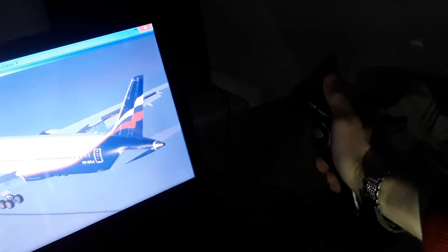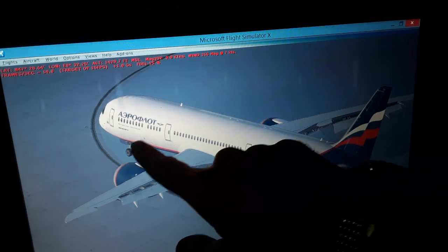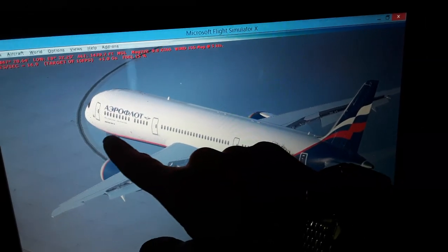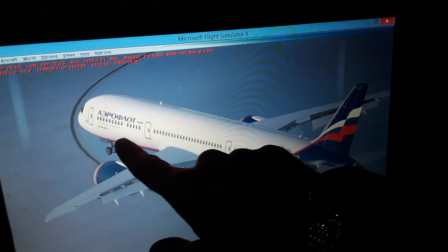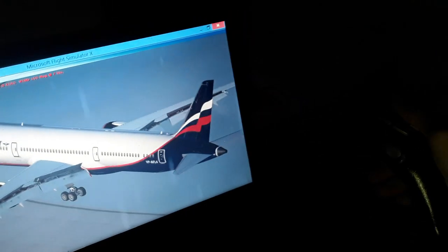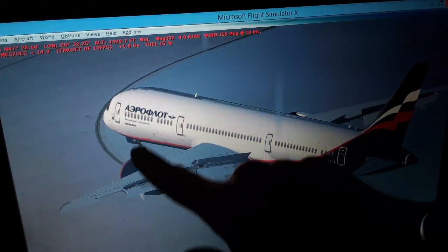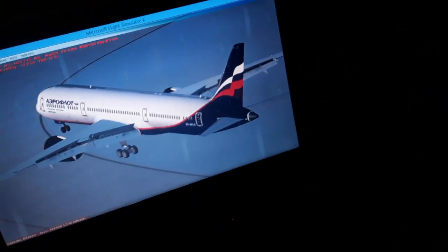So as you increase your airspeed, the deflection of the nose wheel decreases, as the rudder is more aerodynamically effective. So above 45 knots it decreases from 76 degrees left and right to 7.6 degrees left and right, and then above 78 nautical miles per hour or 144 kilometers an hour in takeoff, the nose wheel deflects to 0, so it's locked to the 0 position. So you have only the rudder aerodynamically effective above 144 kilometers an hour.